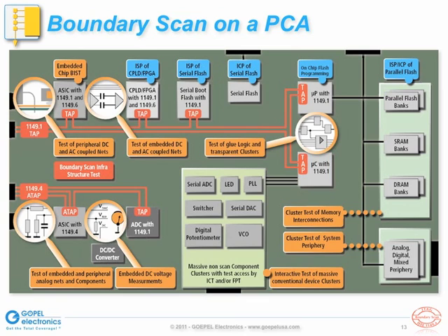The test of connections between boundary scan I/O pins is called Interconnect Test or Connectivity Test. Such interconnect tests often include what we call transparent clusters. The transparent clusters are one or more devices that do not provide boundary scan capabilities, but can be seen as transmitting signals from one pin to another. Examples are unidirectional or bidirectional buffers and bus switches, serial resistors, and even simple logic gates.